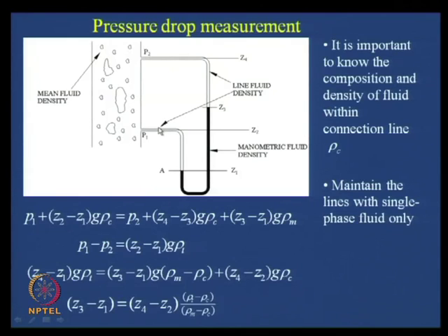Okay. I do not know whether you have been told this during your experiments or not, but it is a norm to first fill it up with water, then see that both levels of the manometric fluid, the mercury, are at the same level. After that you start the experiments.